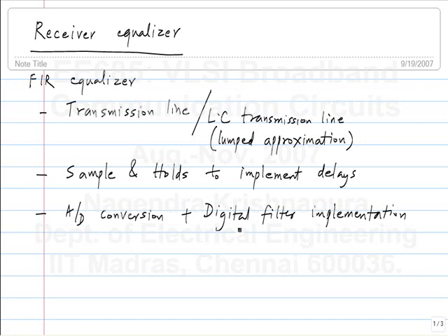So you can look at the equalized signal and somehow do something to it, or at least see whether it is ideally equalized or not, and do something to the coefficients so that the output of the equalizer becomes more or less ideal. More or less ideal meaning at the sampling instance there is no ISI. How would we go about doing that?